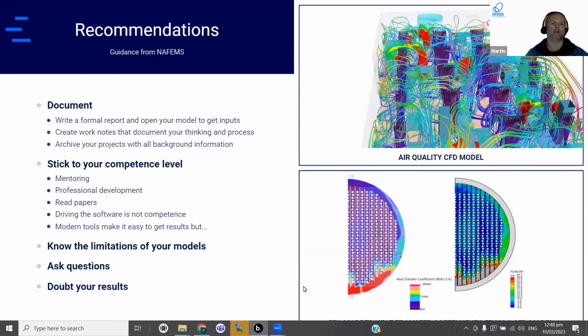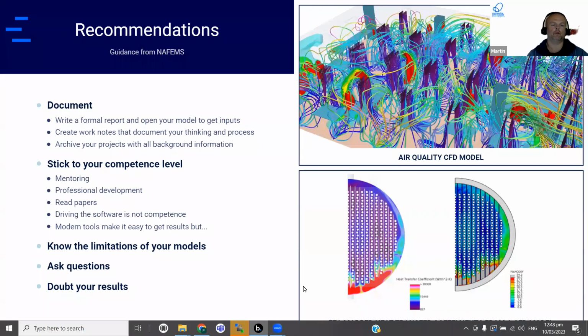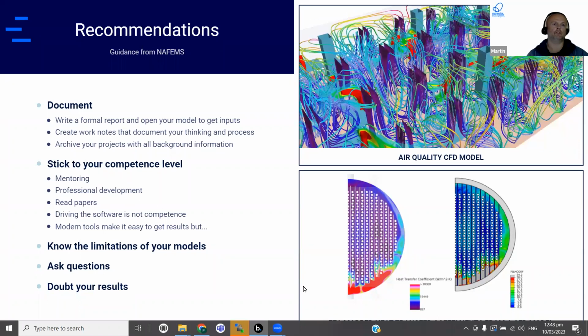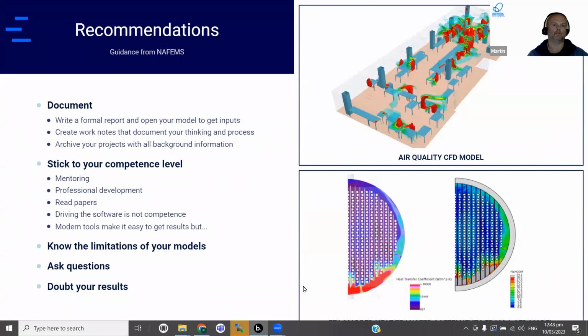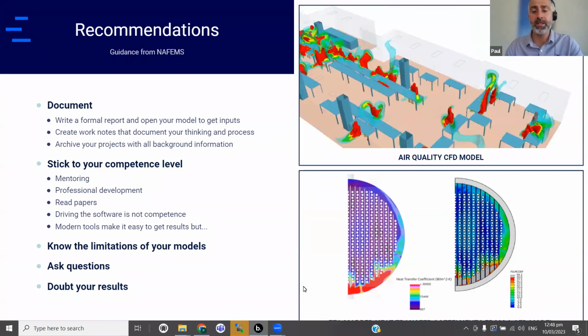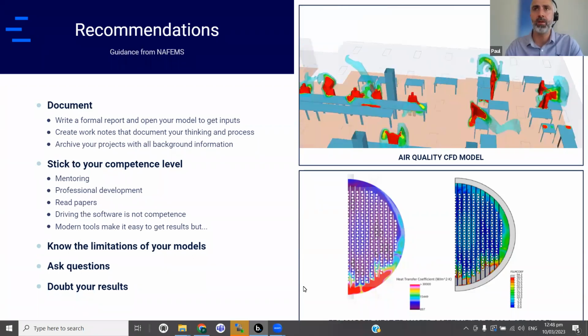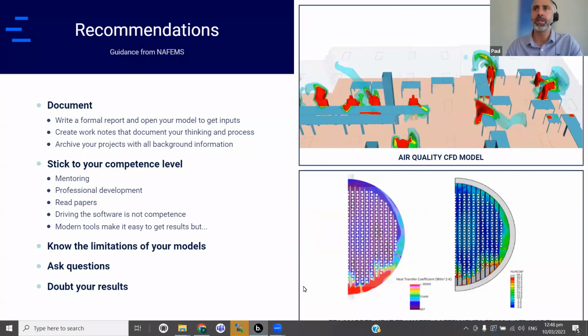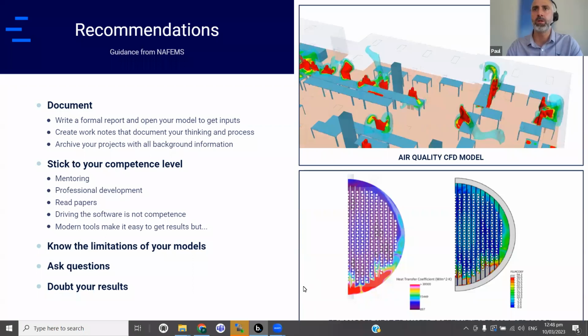And the last one that we have is what analyses do you see being done relevant to the water industry? For example, CFD for optimizing geometry of pump wet wells. Yeah, so CFD in wet wells, I've done a lot of that over the years. And so mainly that's focused on getting good quality flow to your pumps.